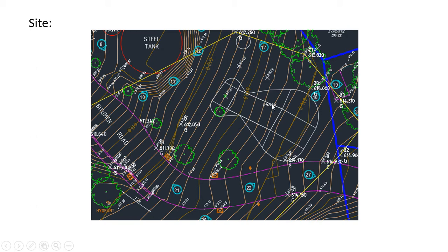This is the footing, which is about 50 square meters. The intention is to create an earthwork volume for this 50 square meter footing, and the lines you can see surrounding it are the feature lines. This feature line footing floor surface elevation has been graded out in Civil 3D. So